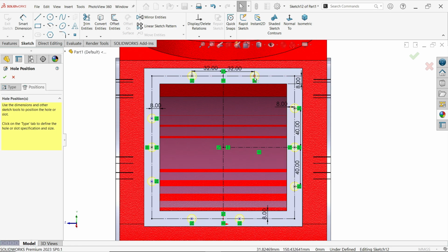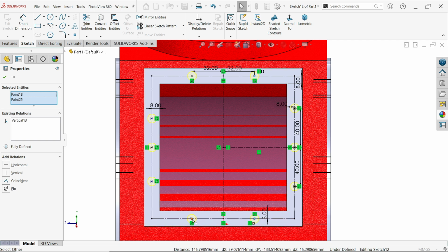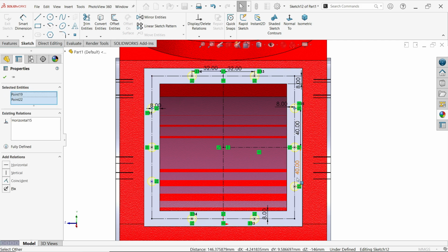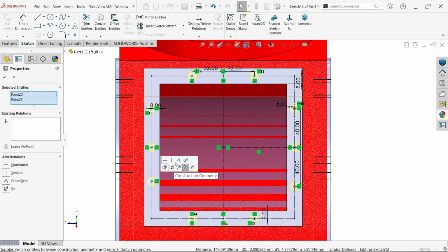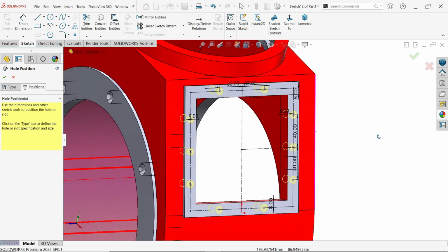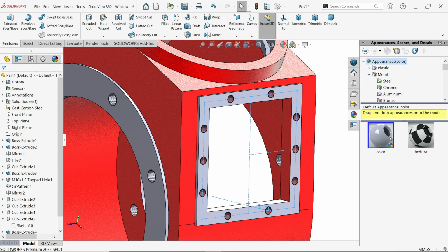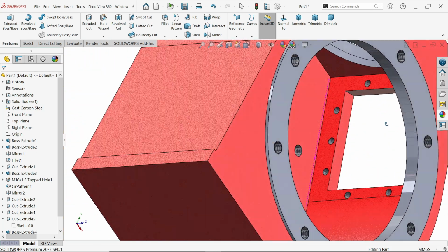okay, let's select this upper one, hold shift key, select this one, vertical. Just create constraint, select these 2 points vertical. Similarly, select this one and this one horizontal. Press and hold shift key, select point 1, point 2 and leave shift key and you will see this popup, or even right side, left side there is. Now this is a fully defined sketch. For the hole I am going to change color. Look, see, this is from inside.